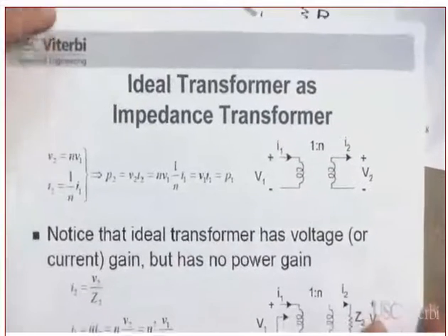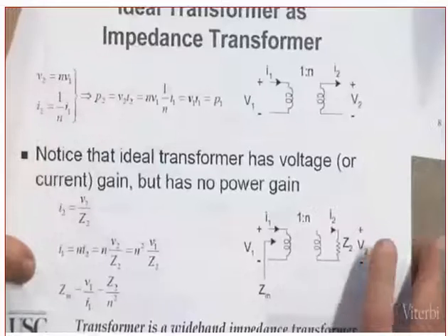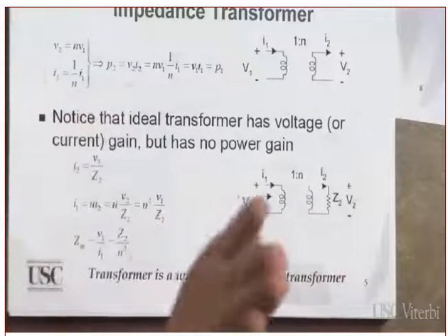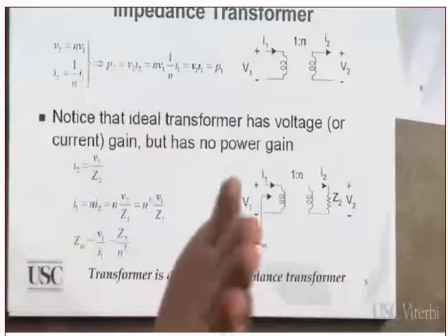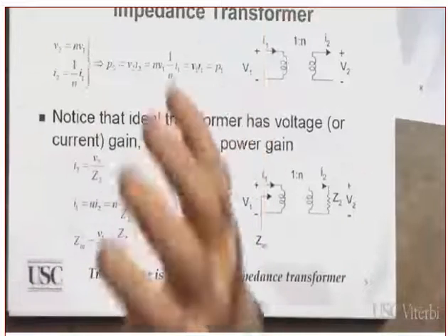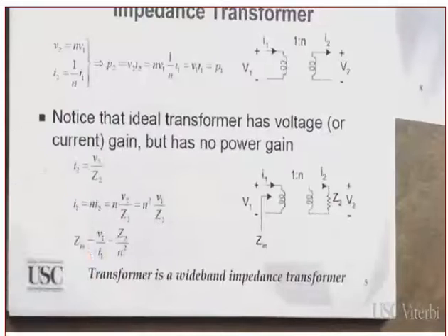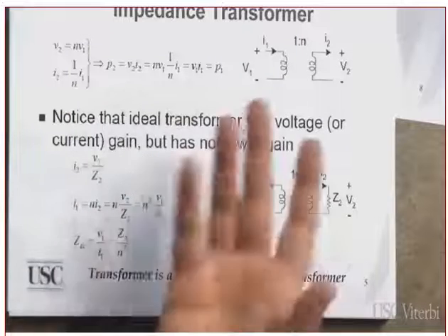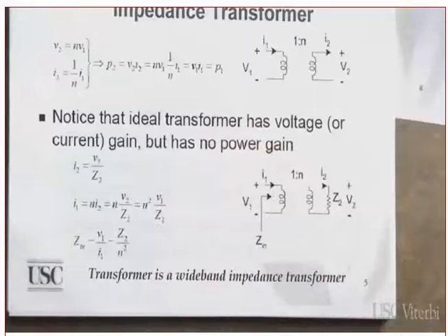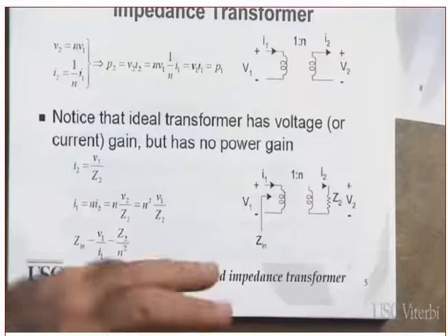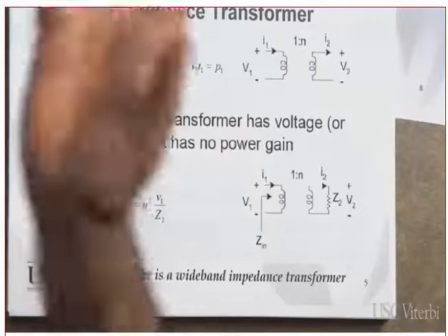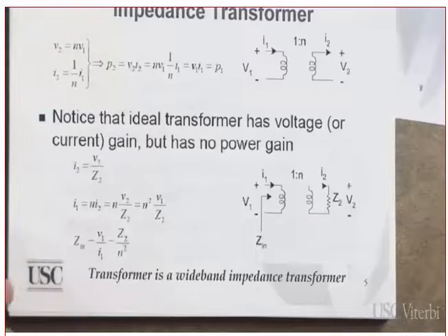Now, let's see how we do the transformation from one resistance to another resistance. At the beginning, listen to me, we are going to assume that both the source and the load are purely resistive. However, the load and the source don't need to be resistive. When we include the non-resistive part, we will lump it with the matching network that we generated.